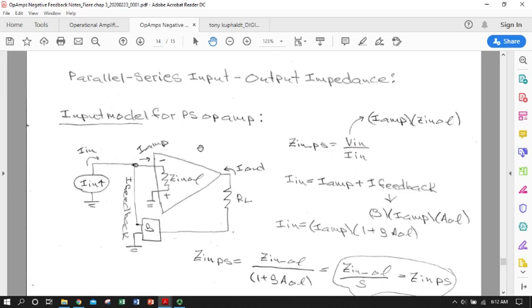So if we look at, again, one of these circuit models representing a simple op amp, the input impedance of it anyway, we're not even looking at the circuitry for the output. So we're just going to say what happens to our effective or closed loop input impedance when we put this parallel series network on. So, not surprising, we're going to define some terms and do some KVLs. So we have our input current signal coming into this point. It's going to split because we've got a parallel input.